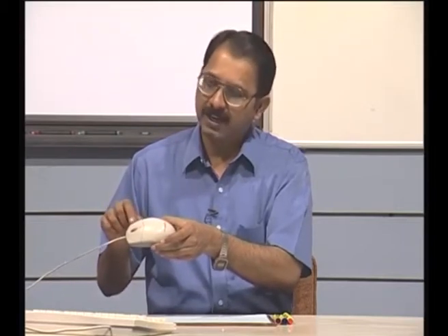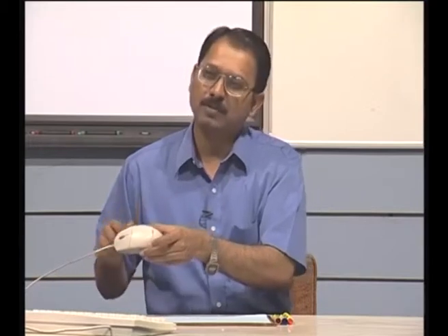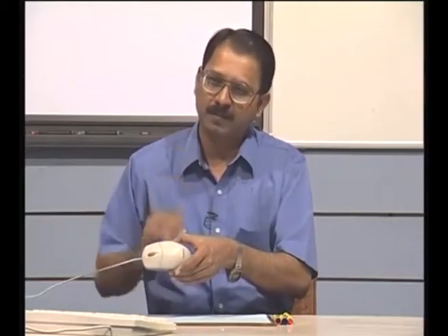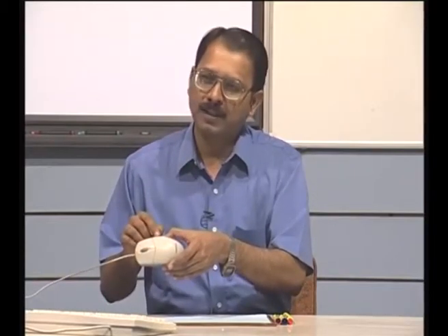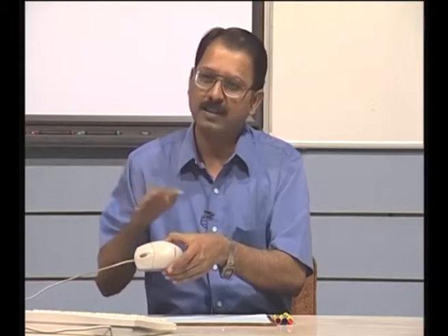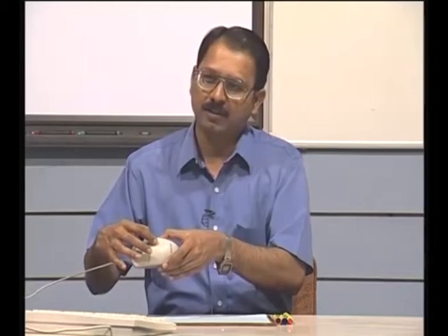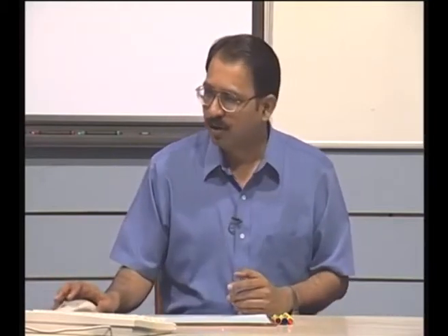It's not possible to take exactly points at those intersections. So I need to sometimes do surface intersection calculations, or if I have two surfaces, I have to blend them with a smooth radius, or if there are gaps between them, I have to see that the contact has been made between these two surfaces with no gaps, which is called stitching in CAD terminology. So you have to stitch pieces of surfaces which are available to you. So all this is a part of a second step.